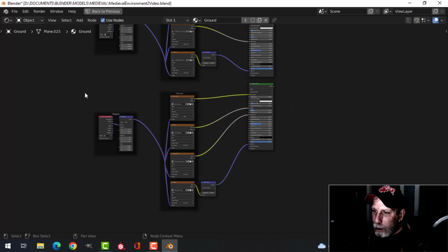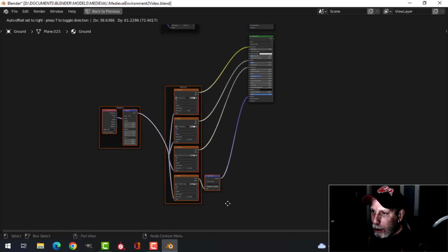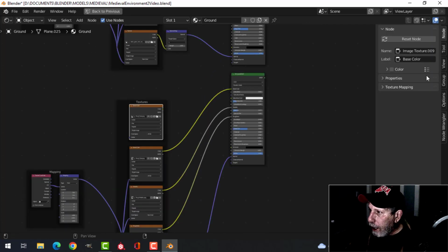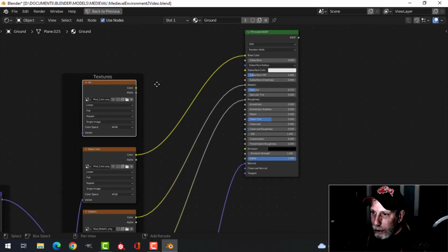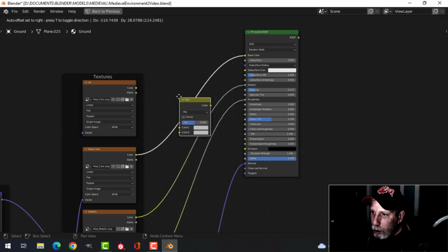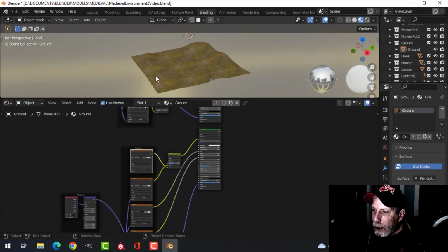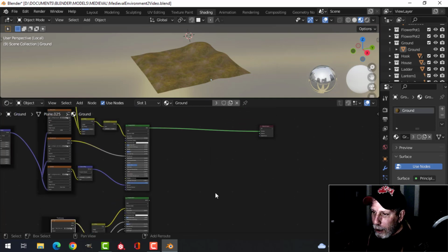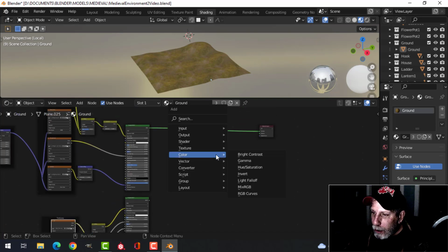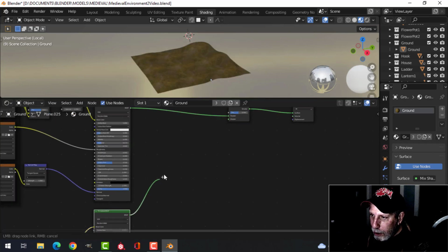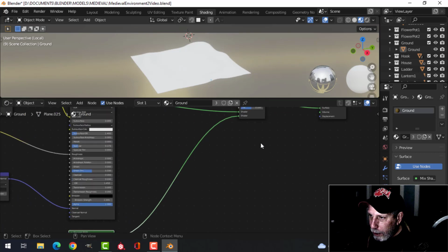So I just want to move these down a bit, because there isn't an ambient occlusion on this one as well. So I'm going to duplicate that and press N. I'll call that AO again, and close that, and then we'll do another mix RGB along this line here, and drag that in here and switch that to multiply. All right, at this point, nothing has changed, and it won't for a bit. We're going to do something here. We're going to connect this, and so I'm going to use a shader, mix shader, drop that in there, and drag this principled BSDF right to there.